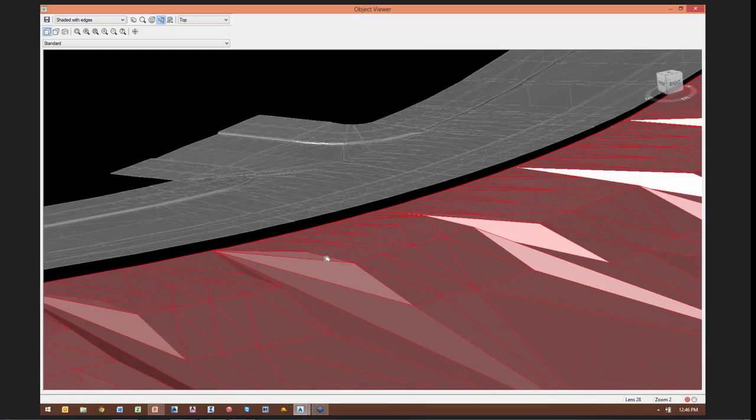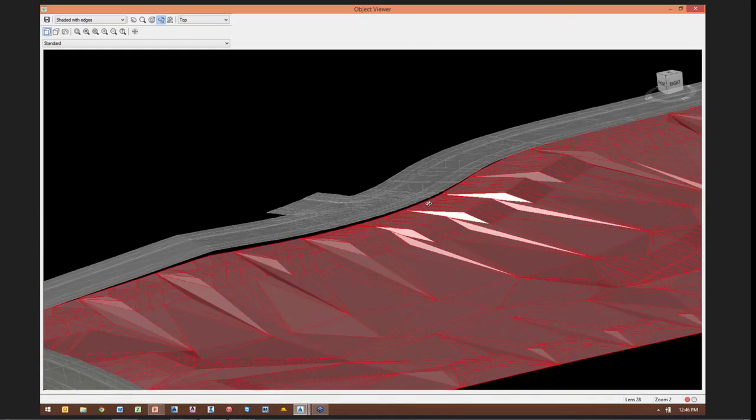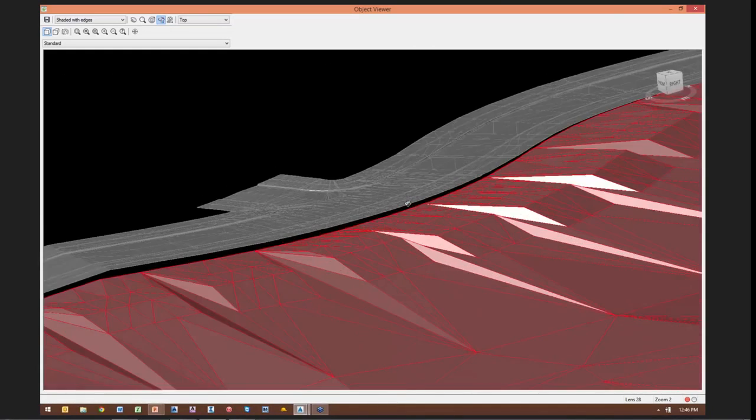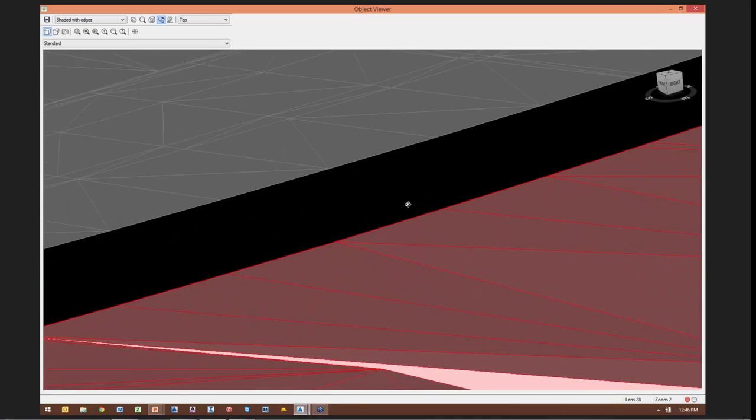Well, how did we set this up? We set it up so that the edge of the lots, the front of the lots, are based on a feature line pulled from the corridor. That feature line is draped or runs right along that corridor surface, so at any point we can pull elevations from the corridor surface and reassign that to that feature line.